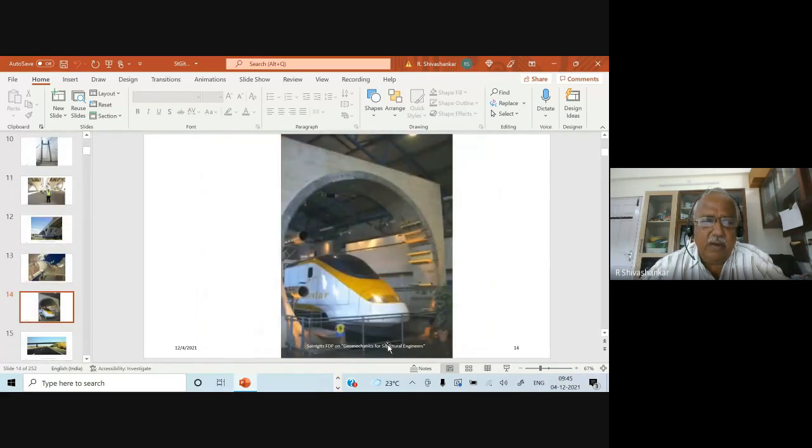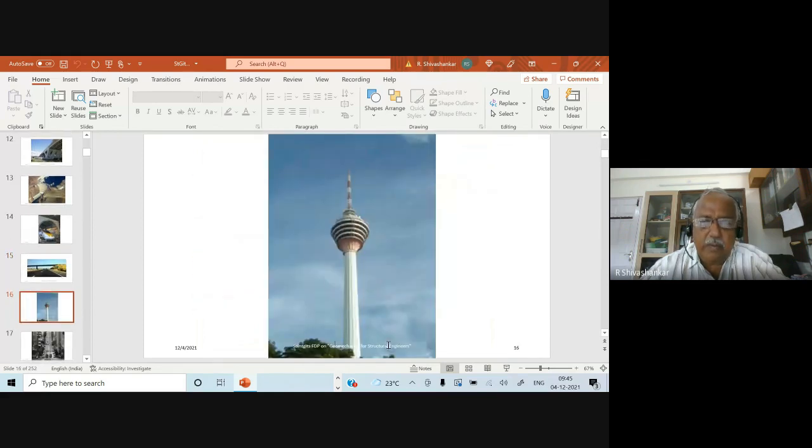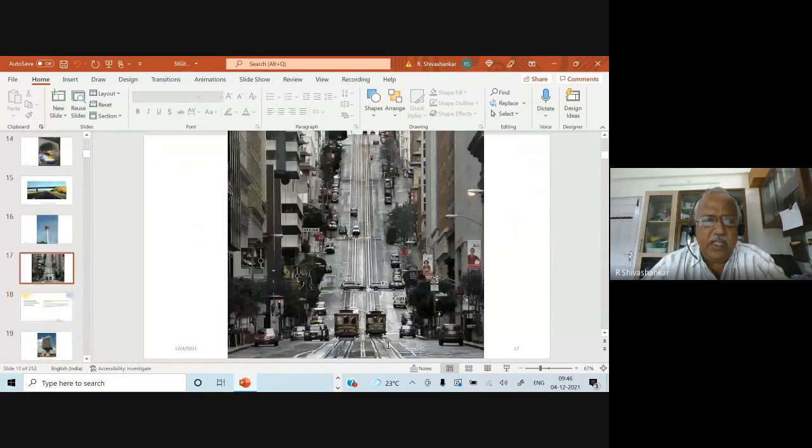We have dams, we have transportation, high speed rail, and over bridges, and we have telecommunication towers. Sometimes we also have to deal with very difficult terrain. And so we cannot say no to any situation, whatever the tough situation, the field situation. I mean, we have to provide a design. And so these are normal structures. These have usual dead loads, live loads, and lateral loads. Lateral loads could be either wind load or earthquake load. We take the worst of the wind load and the earthquake load, not both of them together.